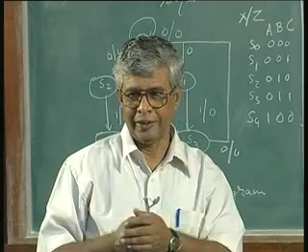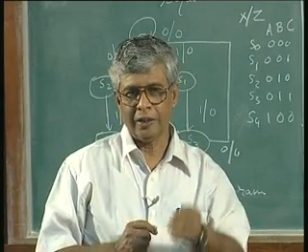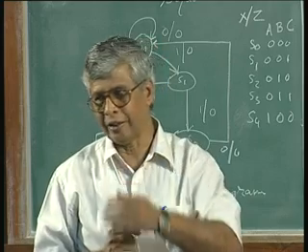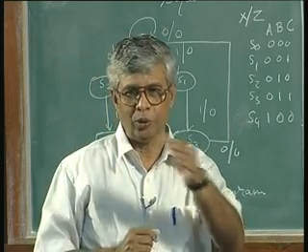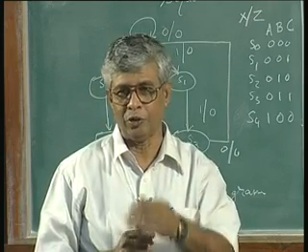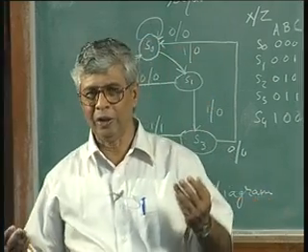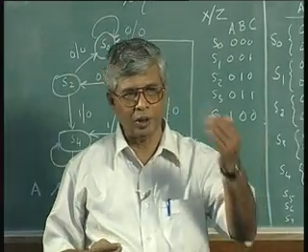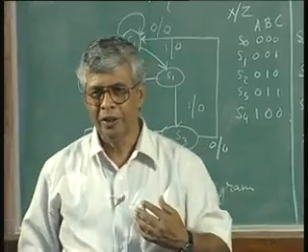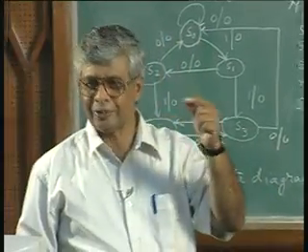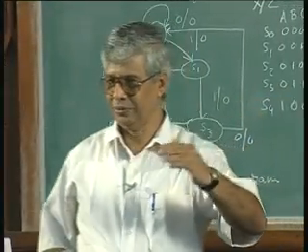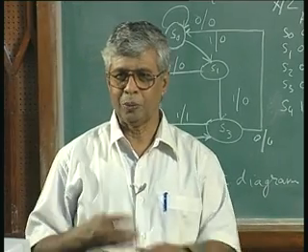Suppose I had a state and the next state is a don't care, and then another state. In both these defined states, the output is 1, and in between, in the don't care state, the output is 0 because we said all don't care states make the output 0. That means I will force an output of 1 to become 0 and then back to 1. If I can retain that 1 as 1, then I will avoid a glitch. So that is a special technique.